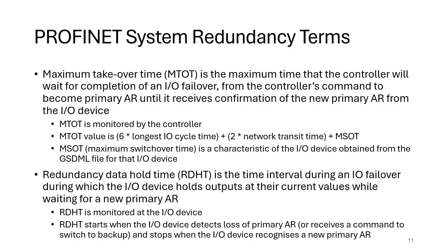So the MSOT is a different characteristic. This is the maximum switchover time, and that's defined for the I/O device. So you can't configure the MSOT. The I/O device itself has that pretty much hard encoded, but you can control the MTOT.